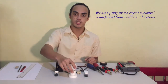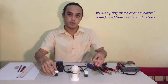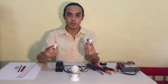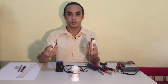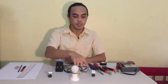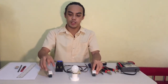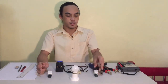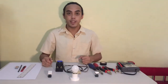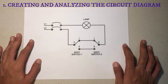We use a three-way switch circuit in order to control a single load such as a light bulb from two different locations using these two SPDT (single pole double throw), or what we call three-way switches. So we can use either of the switches to turn this light bulb on and off. If we click this, it will turn on, and if we click the other switch, it will turn off, and vice versa. We begin by creating and analyzing the circuit diagram.